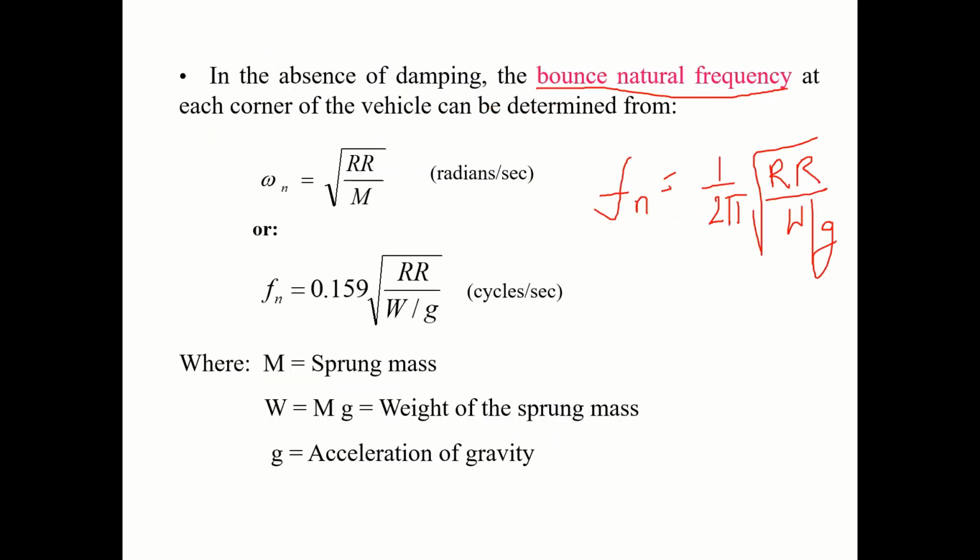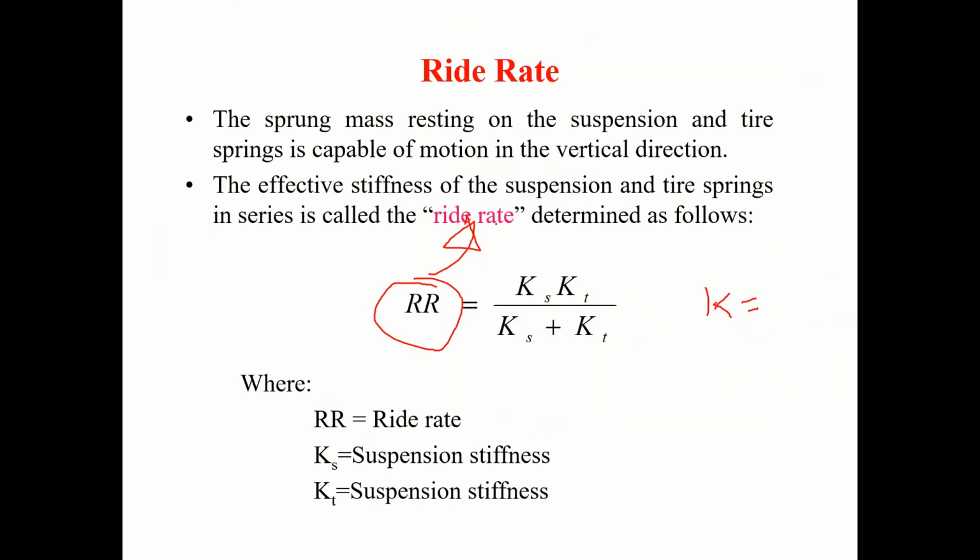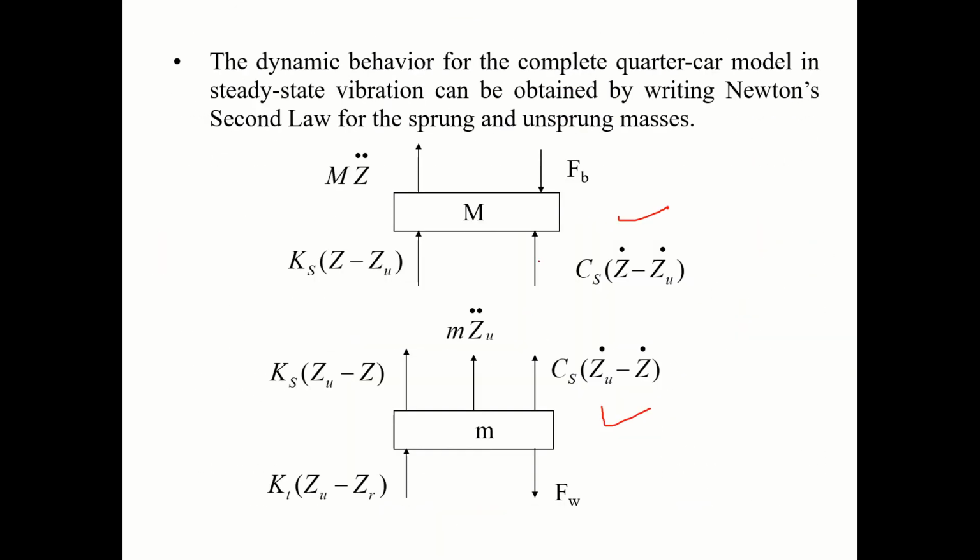Now on the sprung mass, you can clearly see that there is the inertia force, that is 1. This is the suspension stiffness force, and the damping force: 1, 2, 3, plus FB, so 4 forces should be acting. Only FB is acting downwards, all other forces should act upwards. Yes, FB, 4 forces. Inertia forces oppose the motion. This is the stiffness force. This is the damping force.